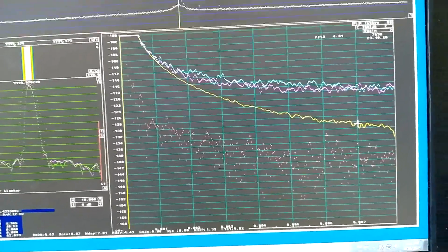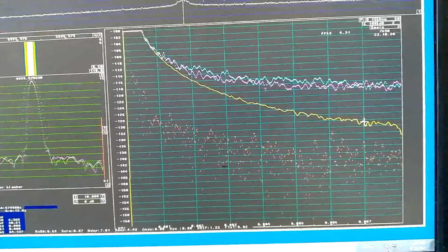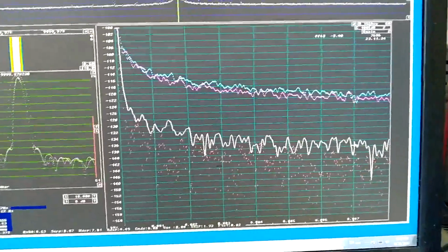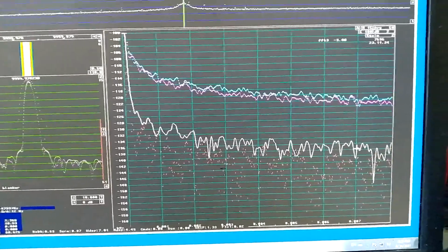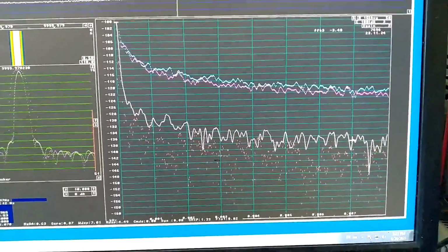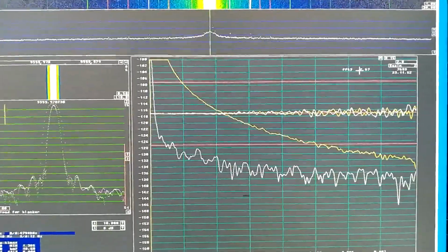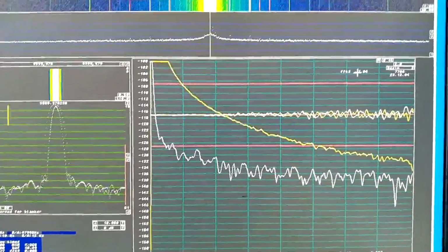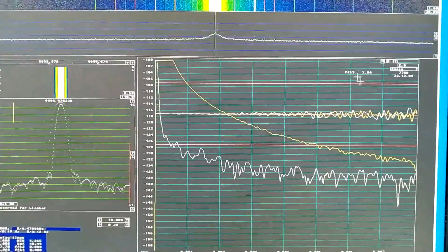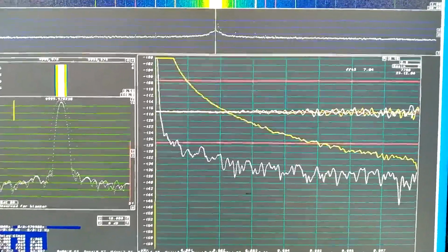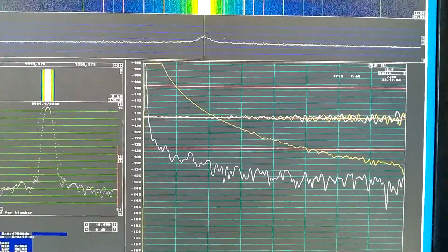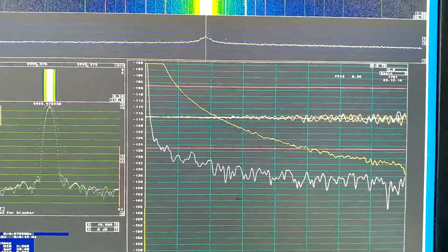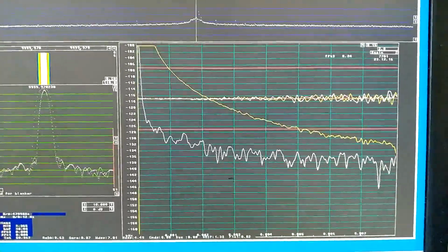And at 7 Hz maybe it is a little better even. And the same is for the amplitude noise. I don't see any difference from without the limiter. And the amplitude noise and the phase noise, they are essentially independent. The little noise we see here is just the poor accuracy of the amplitude noise, probably. So there is no correlation between the modulation types anymore.